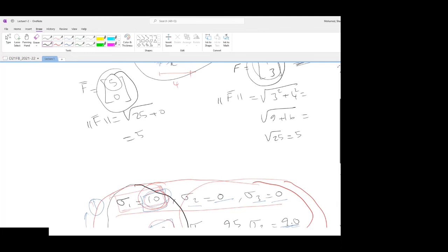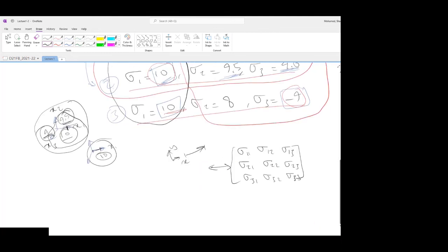The stress can be projected into a different coordinate system, and this can be projected into the principal coordinate system where you have sigma 1,1, and then 0, 0, 0, sigma 2,2, 0, and 0, 0, sigma 3,3, which are basically the numbers I've talked about just above.